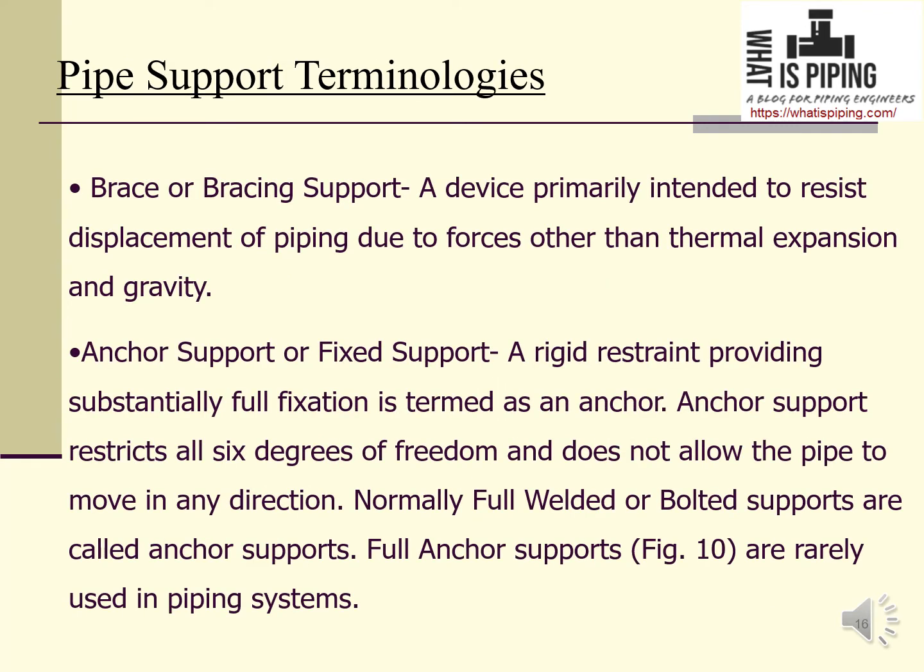Now we will learn about various terminologies used in piping supports. First is brace or bracing support. Brace or bracing support is a device that is primarily intended to resist displacement of pipe due to forces other than thermal expansion and gravity.